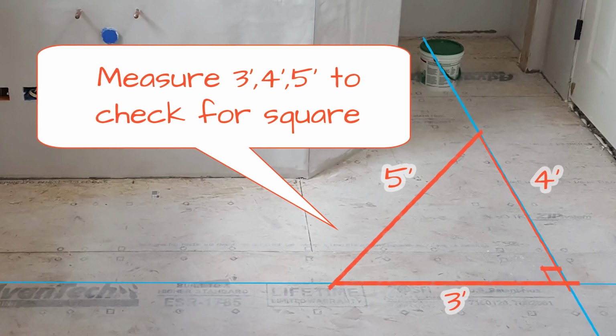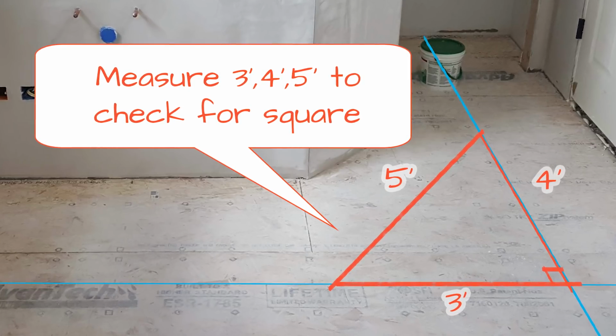You can also double check the angle using the 3-4-5 rule, also known as the Pythagorean theorem. So basically what that states is a squared plus b squared equals c squared in a right triangle. So you can also just use 3-4-5. You measure 3 feet along one distance, you measure 4 feet along another distance of the triangle, and then the diagonal should equal 5 feet. And if it doesn't, you just need to adjust your angle slightly in order to have that perfect 90-degree angle.